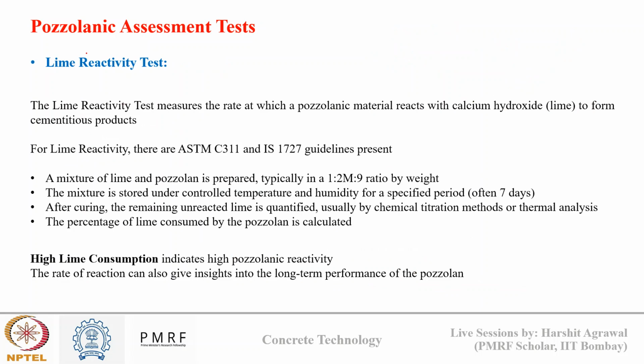Second is the lime reactivity test. This test measures the rate at which pozzolanic material reacts with calcium hydroxide to form cementitious product.